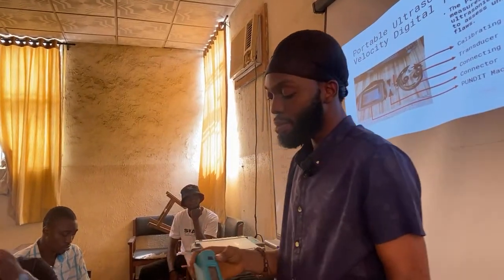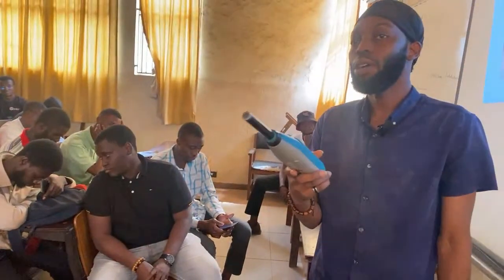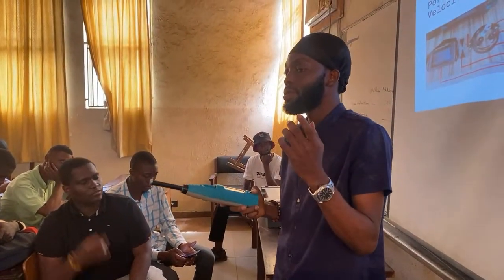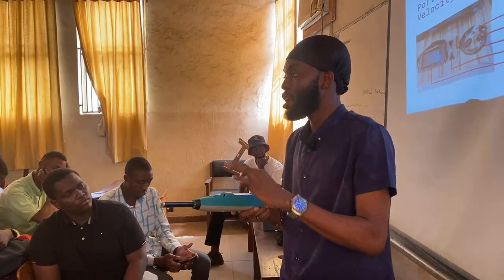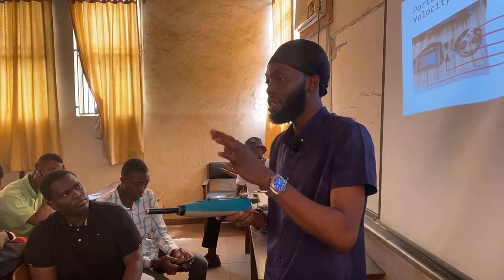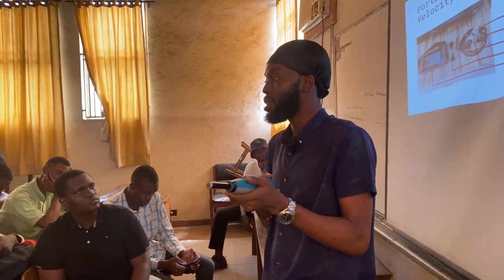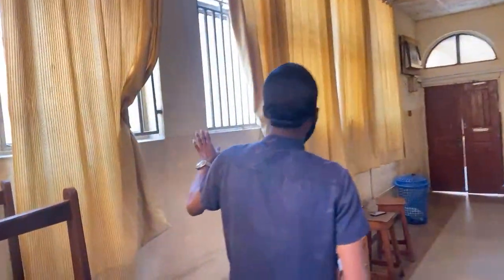So now, for each structural element that will be tested, I'll be making 10 impacts. I will show you the Q value, that's the rebound number, the impact counter, and everything, after I've done the 10 impacts on the structural element. So let's just assume this is an unrendered surface. I want to check the surface hardness.